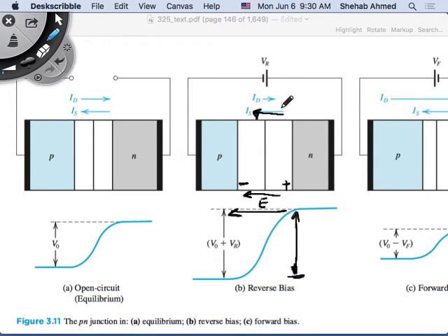Remember that if you limit diffusion, you decrease current. For an open circuit, what you're saying is correct. When diffusion happens, I create this depletion layer with uncovered charges, which creates a voltage and hence an electric field. In open circuit conditions, the diffusion current and saturation current balance themselves out, so that no current is flowing. They're equal to each other.